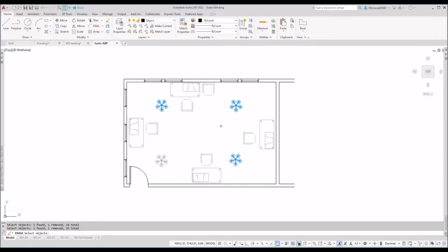You can also put a window around them with the shift key held down, or a lasso around them, to deselect them. So the shift key is held down. You've got all your selection tools, but they're all working in reverse, look, with the shift key held down. Release the shift key and it goes back into add mode again. So I can go and add them back in again, like that.